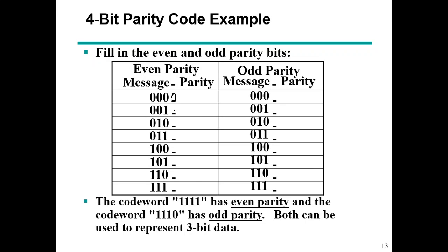What should be this particular bit? We also call it the parity bit. So this bit should be 1. Why? Because this is an even parity code, and the number of ones is always even. Therefore this should be 1 so that the number of ones is 2, which is even. So this bit should be 1 so that the number of ones stays 2, or even.